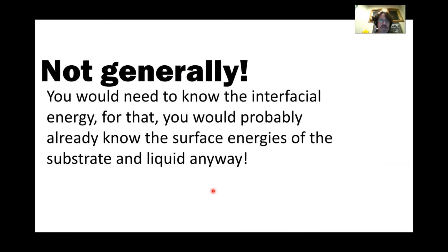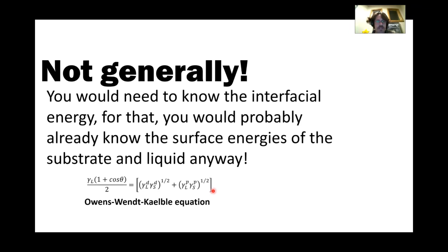Not generally. The reason is you would need to know the interfacial energy. For that, you would probably already know the surface energies of the substrate and the liquid anyway. So you generally do not use Young's to calculate the surface energy of a surface or the liquid for that matter. What you use typically is a more complex equation, and here's an example.